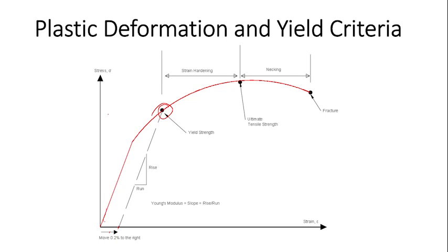Okay, so more number of dislocation will generate, and then these dislocation will start interacting with each other, and they'll start pinning. Okay, these things you will learn in material science. They will start pinning at some point. So because of that, further deformation will be arrested. Suppose you have plastically deformed your material here, so there will always be some plastic strain present in that.